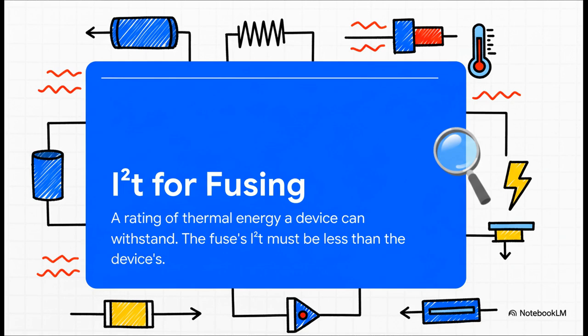But you can't just grab any old fuse. You have to be strategic. You need to look at a rating called I squared t. That's I²t. It basically represents the total amount of thermal energy a device can handle before it's destroyed. The rule is simple, but it's absolutely critical. The I²t rating of your fuse must be less than the I²t rating of your semiconductor. That way, when a fault happens, the fuse blows first, saving your much more expensive power transistor.